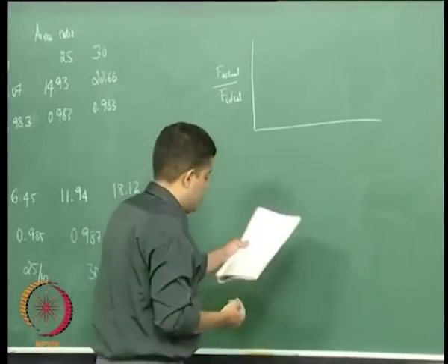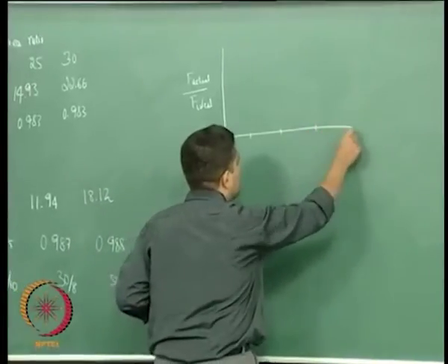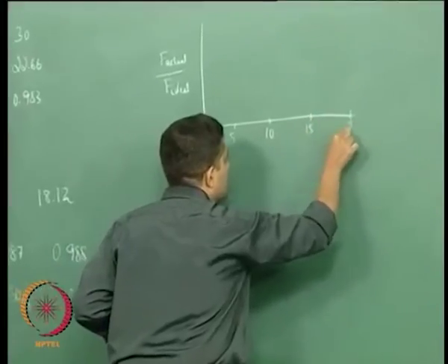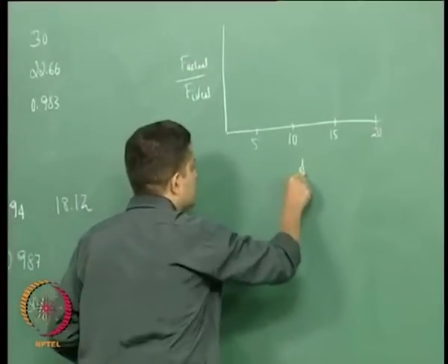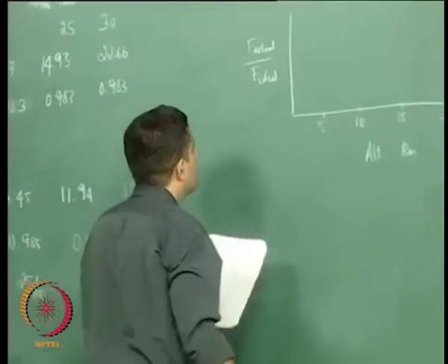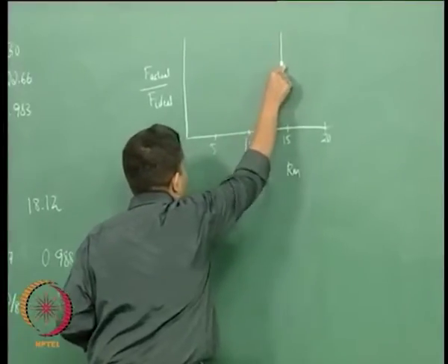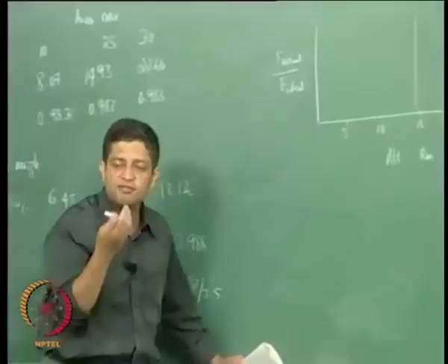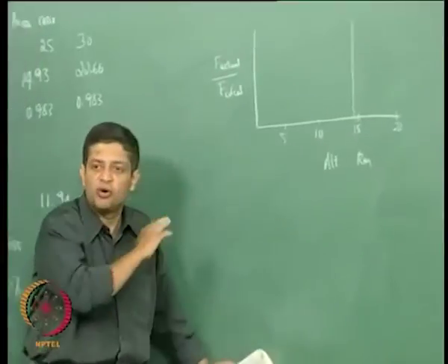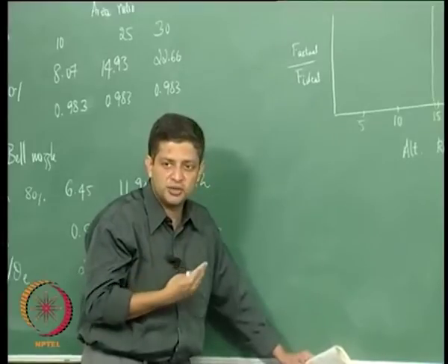So, depending on what is the altitude, let us say you have a bell nozzle and a conical nozzle designed for some high altitude around 14 kilometers or so, then it will give its best performance there, and what happens to it at other altitudes is what is of interest to us, right.